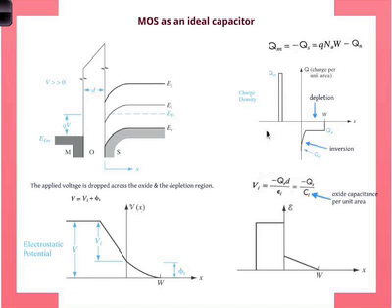said, essentially a parallel plate capacitor where you have metal on one side, oxide, and on the other side you have a semiconductor. So we can model this fairly carefully. The band diagram is exactly the same as before. In this case, you have strong inversion. The applied voltage is very strongly positive, so you pull the bands down so much that you have a nice n-type channel right there.